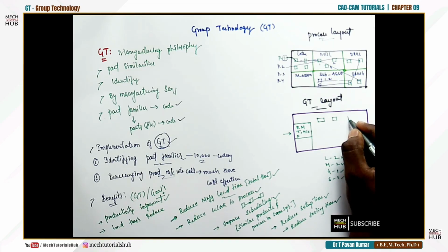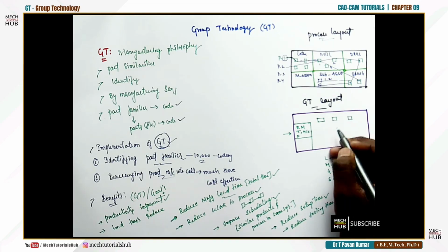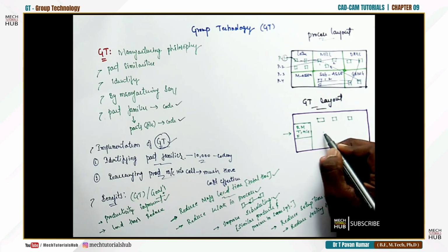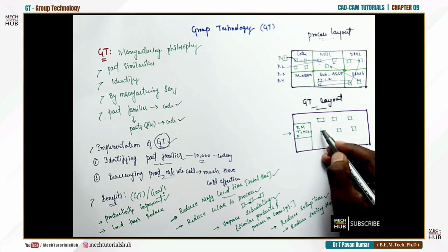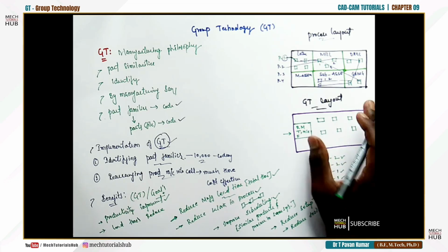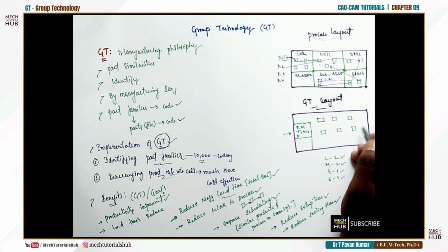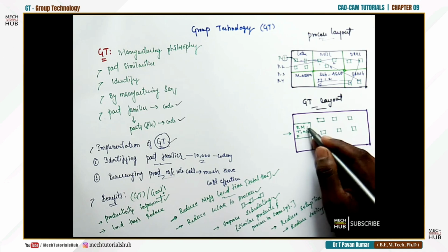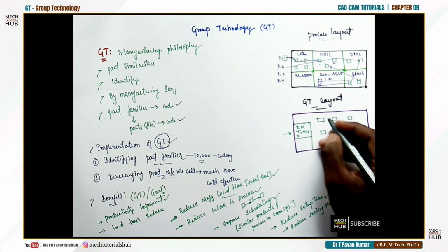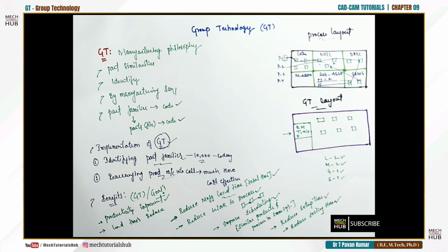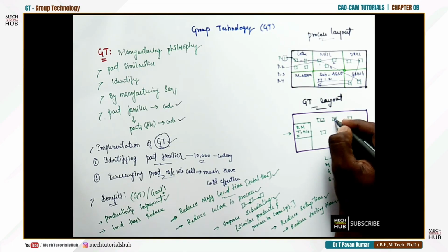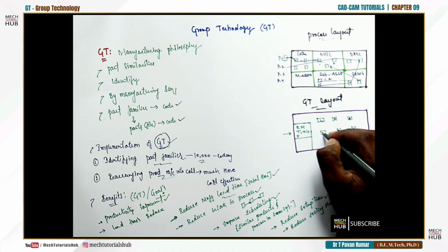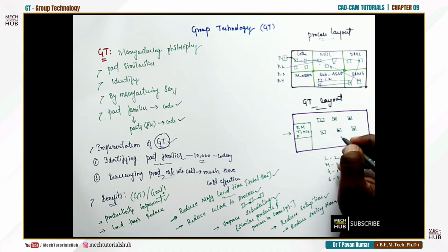Accordingly, we will try to place the machines. If required, some work has to be performed in parallel, so we will place the machines in parallel also, okay. And this arrangement will change from project to project, it will not remain the same, the complete layout will change. Once the raw material is procured, the first one, maybe, is a lathe machine, followed by a drilling machine, a grinding machine, a milling machine, one more grinding, one more lathe. Two works can be performed in parallel at a time.